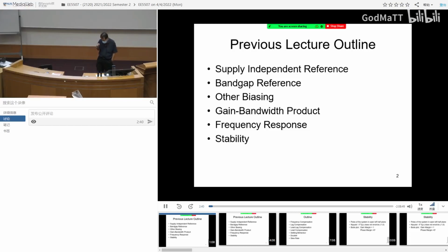And for a lot of technologies, a very key, important parameter is called the unity gain frequency, FT. I hope you still remember my advice: if you know the FT of the technology, usually you can deduce what kind of operating frequency range the technology is good for. If the FT is, let's say, 100 gig, you know that circuits should be no problem designed all the way up to 10 gig.